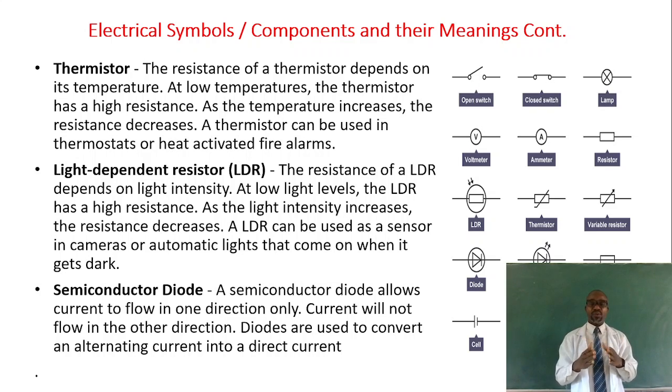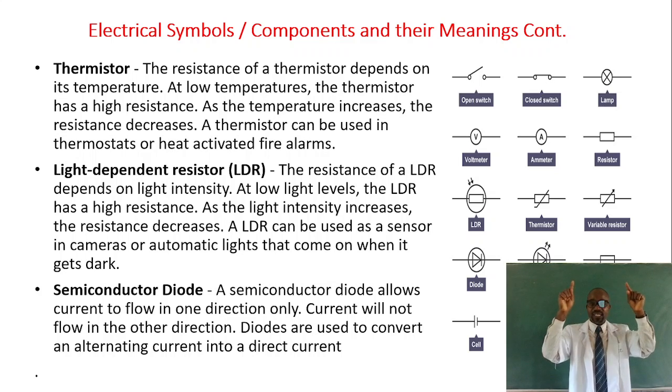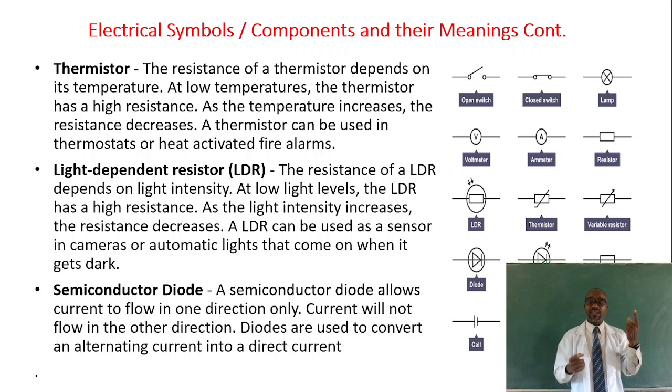You connect what we call a voltmeter. And you are going to do this connection in parallel with the lamp. With what? In parallel with the lamp. The voltmeter has to be connected in parallel with the lamp in the circuit for you to be able to measure the potential difference across 2 points. As I said earlier, A and B, or any letter of your choice.